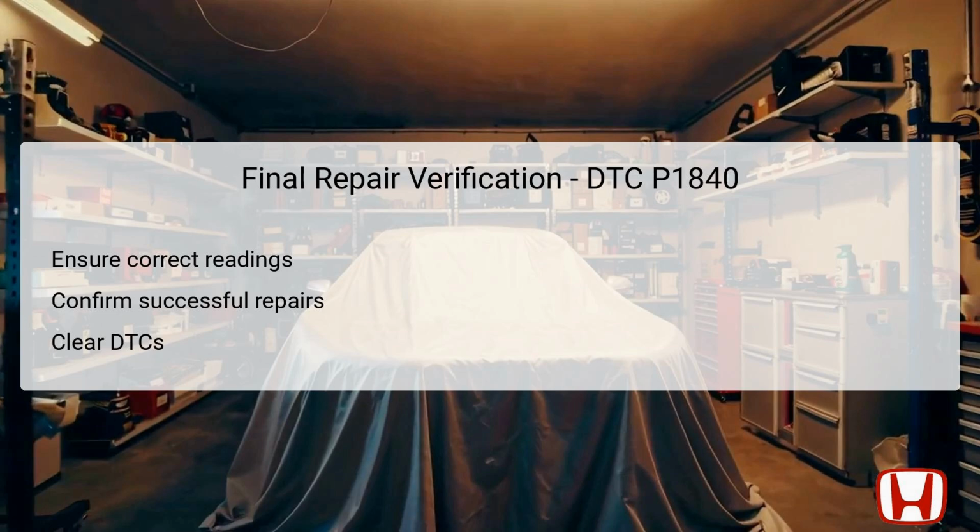Upon confirming that the appropriate repairs were conducted, it's essential to clear any diagnostic trouble codes, DTCs, stored in the system. This step ensures that no residual faults remain and allows for a fresh start in monitoring the vehicle's performance. By rechecking the system's behavior post-repair, the technician can confidently verify that the issues associated with DTC P1840 have been resolved successfully. A comprehensive final check minimizes the risk of overlooking any hidden faults and upholds vehicle reliability.